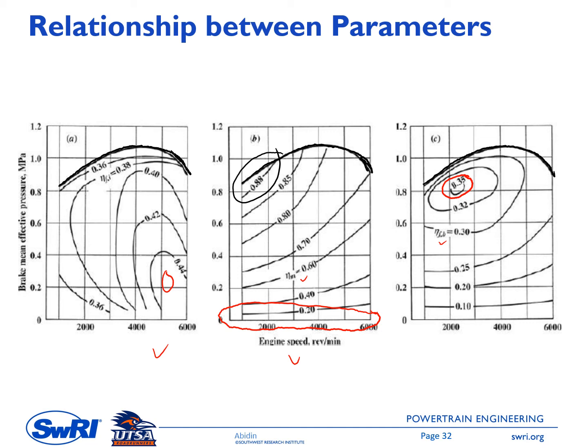So the engine thermal efficiency is maximum around this island, and the other lines show the iso-line values, meaning the engine thermal efficiency is constant along each line. We will learn this engine data map in more detail, I think, in the last chapter of this class.